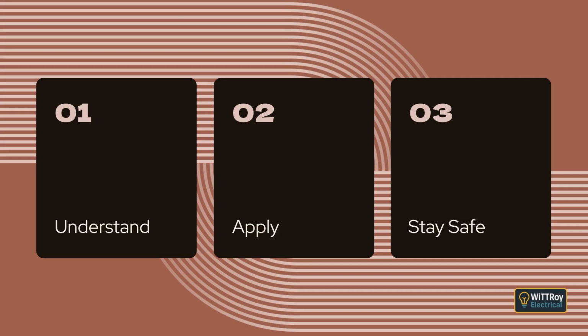Clause 3.9.7.5, Low voltage track systems. Low voltage track systems must be installed so the track is open to view for its full length but does not need to be visible from every position. The system must be positioned to reduce dust entry, and the supports must be appropriately designed, correctly spaced, and arranged so the track is held securely without sagging.